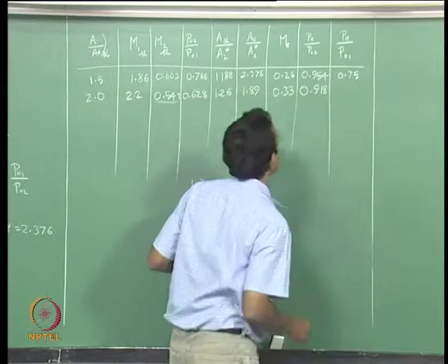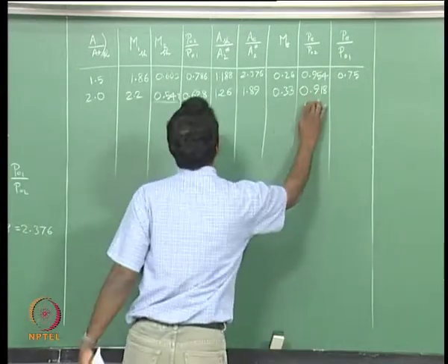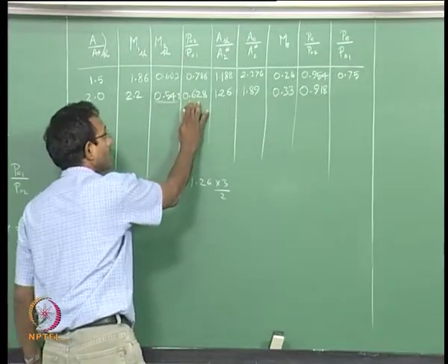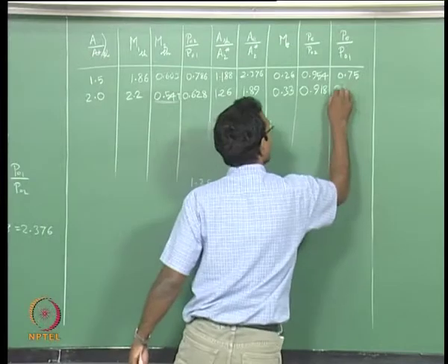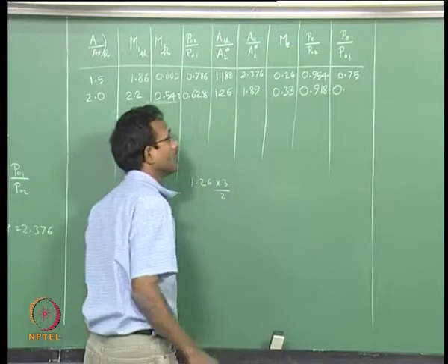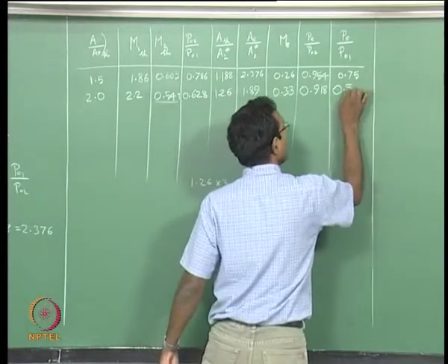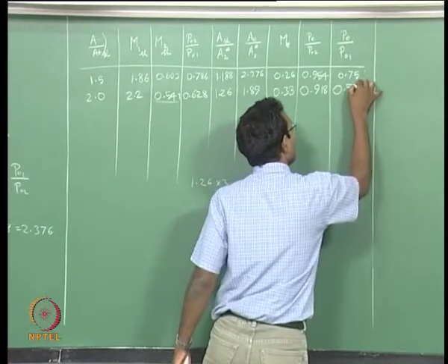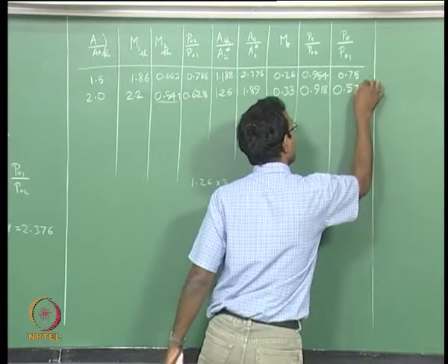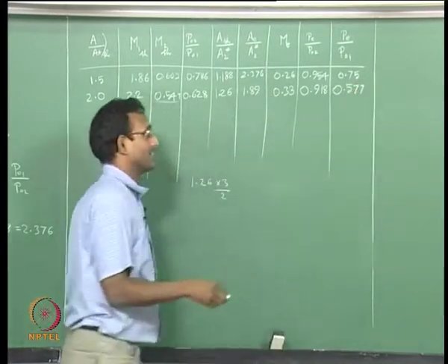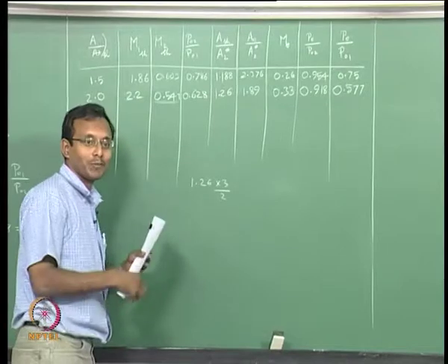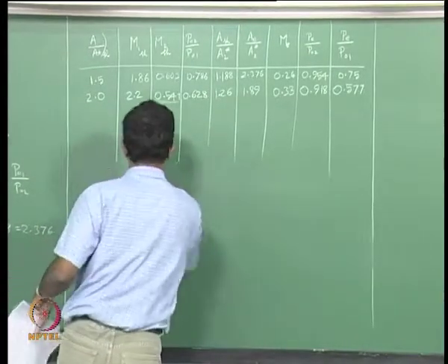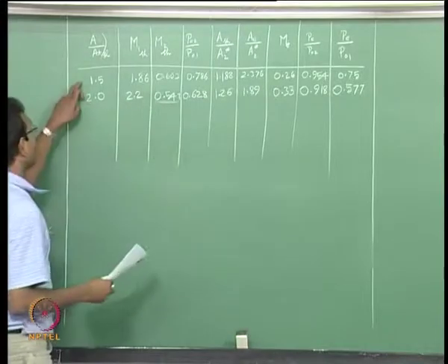0.918. Okay. Now I have to multiply the 0.918 with my P02 by P01, 0.628. Multiply this with this. What will be the number? 0.577. That's fine. Three decimals is probably too accurate. It may not be that accurate when we calculate stuff. Two decimals are really enough. So yes, we have moved in the correct direction.